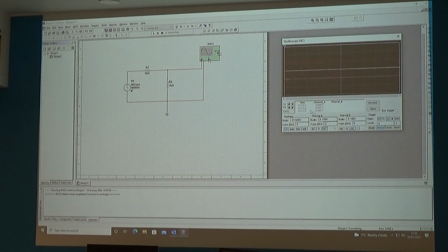So where it says time base on the bottom left hand corner, look at my cursor, what I can do down there is sample a bit quicker, look at some smaller chunks of time, and then I can start to see the waveform. So play about with that time division, and you can see that you can zoom into the wave, you can zoom out from the wave, and so on and so forth, yeah?